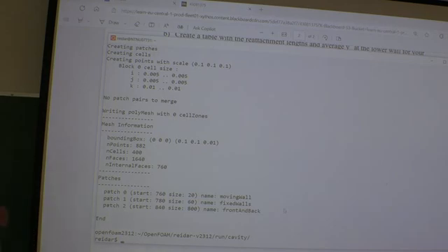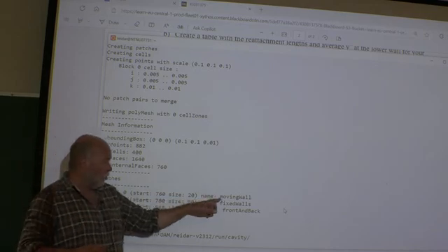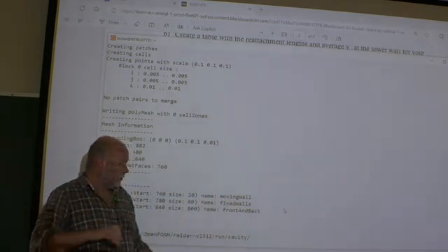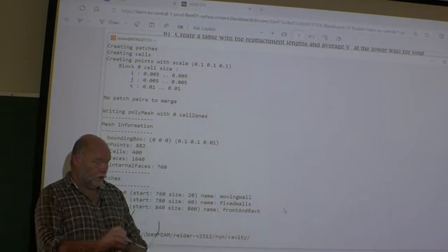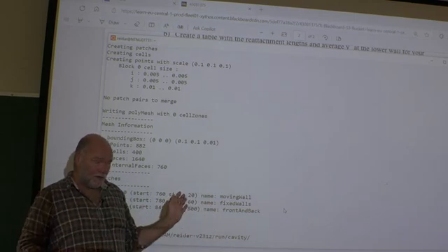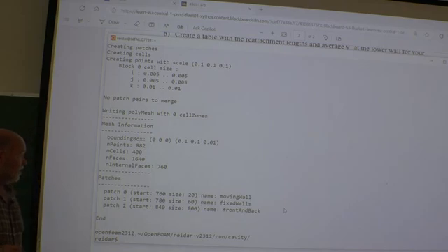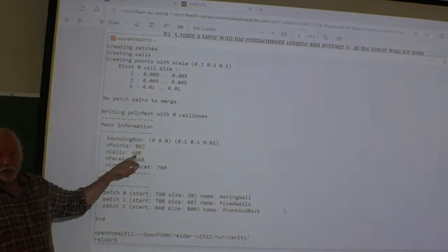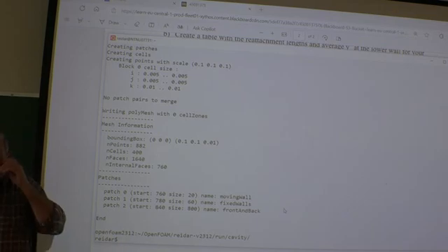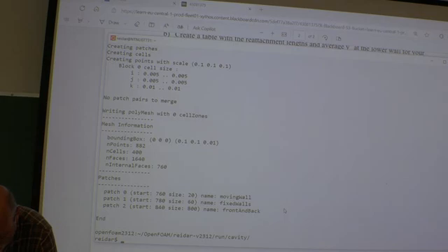If you can recall the cavity case, you have one top wall, he's moving with a constant velocity. Then you have 3 fixed walls, and then front and back is a 2D case. And we only have 20 by 20 cells, so it's a quite crude one. But never mind. So here we now have created the mesh.